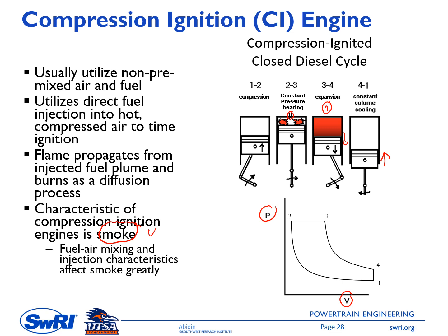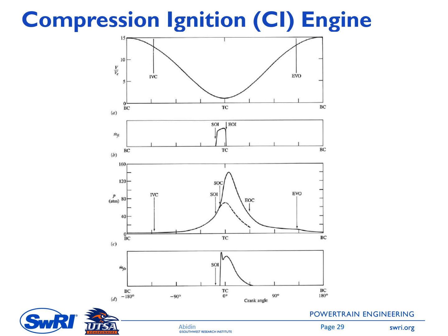In thermo 1, I think you know this PV diagram for the diesel or compression ignition engine. So we assume a constant pressure combustion for this diesel engine. And then for the spark ignition engine, we assume a constant volume combustion process. This is the profile of the volume change, and then this one is the fuel introduction, and this one is the cylinder pressure, and this one is the rate of the heat release.